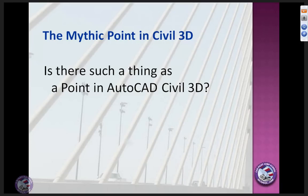I could also talk about things like points in a surface, COGO points, or survey points, or, well, there are actually lots and lots of kinds of things that we refer to as points. And that's not just semantic language. They are actually different things inside of Civil 3D. So a survey point, a point in the survey database, while it may show up on your screen, isn't a COGO point. And a COGO point certainly isn't a surface point, though they may all be talking to one another.